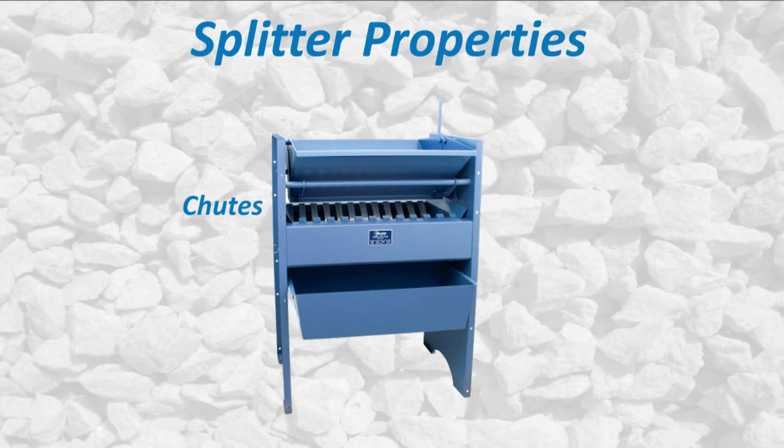The mechanical sample splitter shall have an even number of equal width chutes, not less than 8 for coarse or combined aggregate or 12 for fine aggregate. The chutes shall discharge alternately to each side of the splitter. For coarse and combined aggregate, the width of the individual chutes shall be approximately twice the largest size particle in the sample to be reduced.